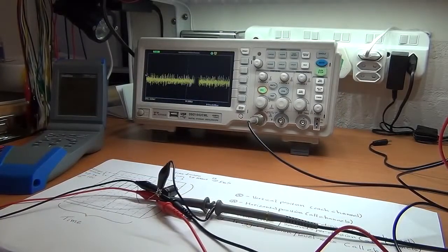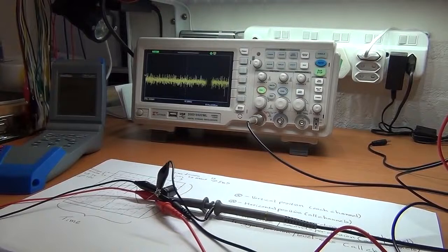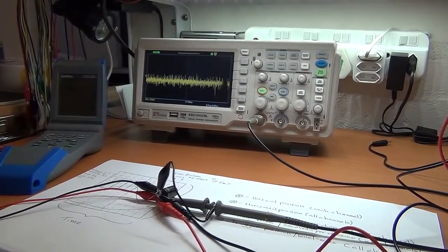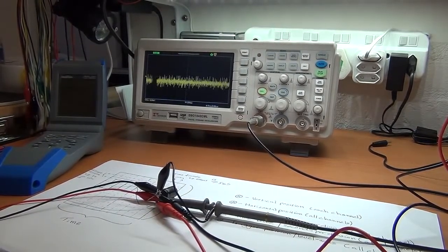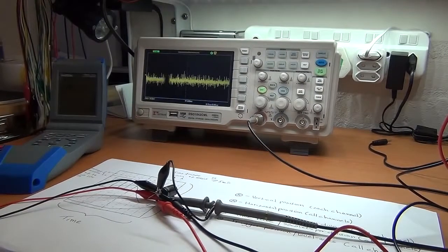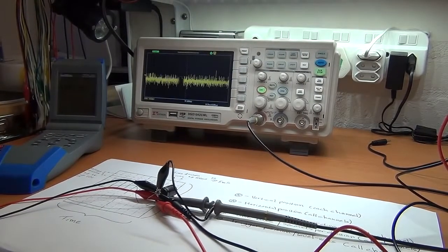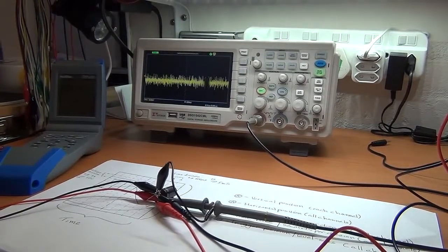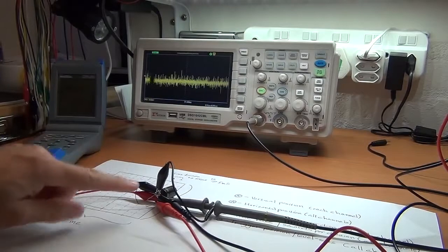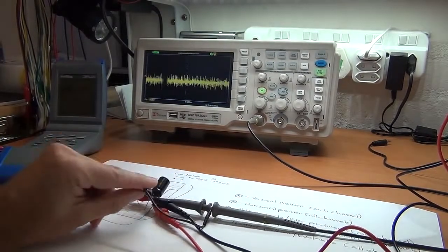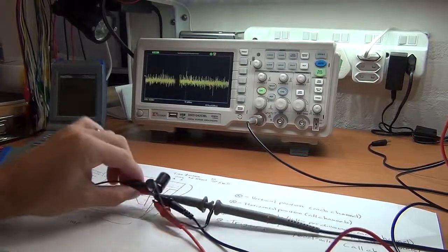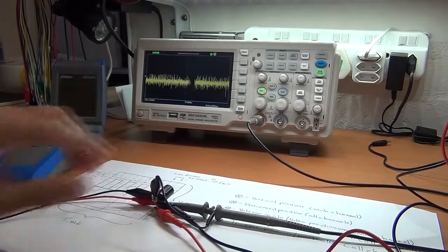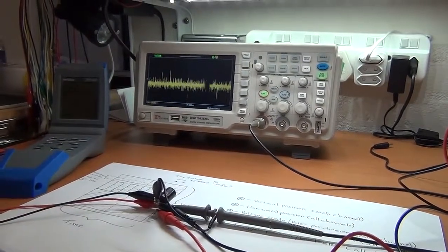Okay, and the last thing I thought I'd leave you with is another feature which we can explore further in the next series on this, which is capturing a signal for analysis. If something's happening very quickly, you may want to capture that little impulse or little signal and then analyze it. So what I've got here is a capacitor of a lot smaller value. It's only 10 microfarad. I've got it hooked up to my variable power supply.